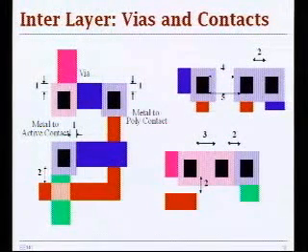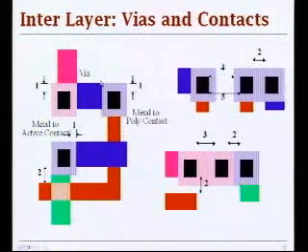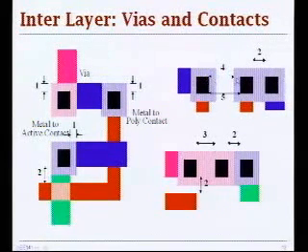How do you create contacts in layout? And also these rules specify, in addition to enclosures and minimum size of these objects, they also specify relative distance between the contacts, and also position and distance of these contacts relative to other materials such as polysilicon in this illustration here.